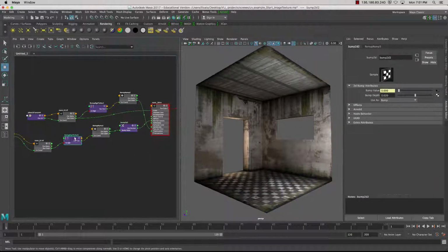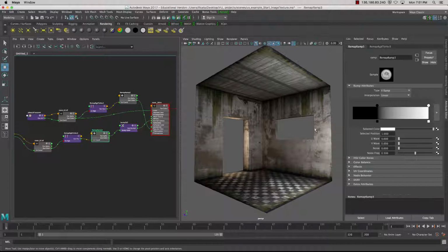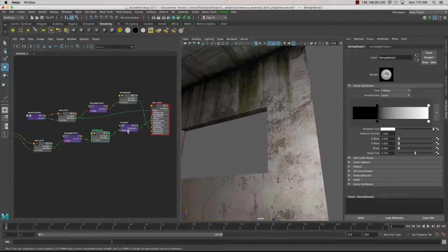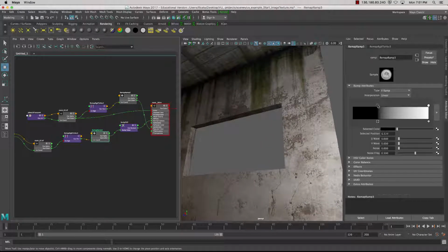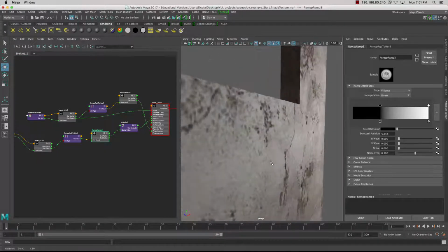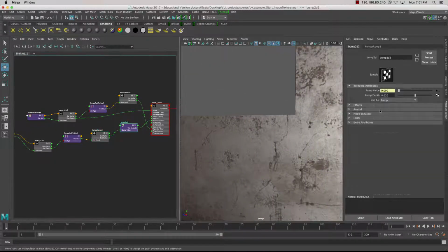In the scene, I've just redone the bump map, and I've again used the same image, but I've used the effects color remap insert, which has added the ramp, and then I'm using the ramp to affect where I want the bump values. So the bump values are really low, but the ramp gives you that extra control, so you can control where the elements are. So in this case, let's just bring up the value so we can see it happening.